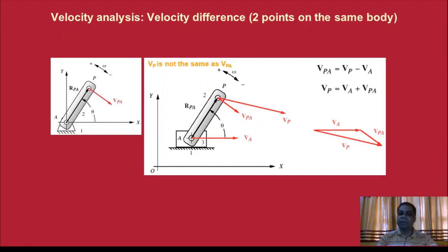When the rectangular slider moves in the right-hand direction in a straight line path, its velocity component is shown by Va. During this operation, because of the movement, the individual velocity component of point P is Vp. But when we get the turning component, that is Vp with reference to A, the velocity Vpa, it is perpendicular, at 90 degrees, to the link connecting A to P.